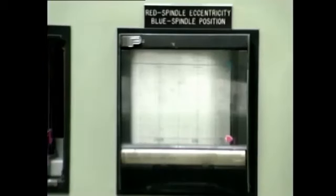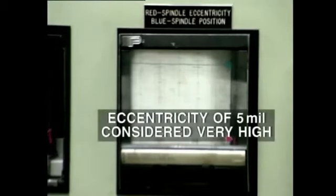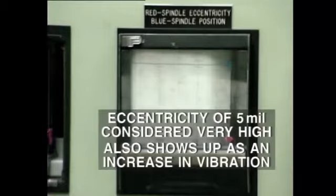The degree of eccentricity is measured and recorded at the operator's terminal or control board. In most machines, an eccentricity of 5 mil is considered very high. High eccentricity also shows up as an increase in vibration at the bearings.